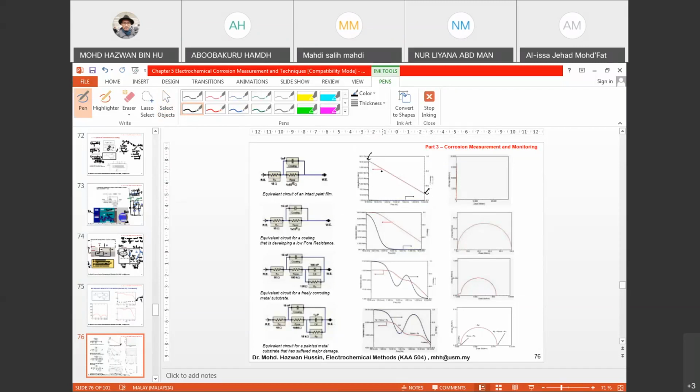So probably you can also have a resistance here. The Nyquist plot is not forming a perfect vertical line, it's tilted a bit, slightly like this. Still we can say that it has a parallel effect, because for series it is normally a very straight 90 degrees, and this one is not really 90 degrees, it's slightly bent. Then you have a parallel design.